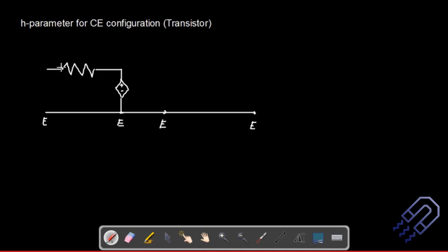That is also important. And then we have an input current. Since it's a common emitter, the input current will be nothing but the base current. So this is IB. And the voltage across this would be nothing but VB. The question is why it is VB? Because the emitter is grounded. You have to assume this is already there; you can actually draw it also. The emitter is grounded, so this is at zero potential, and this is at the potential VB, the base potential. So we can just represent it as VB.